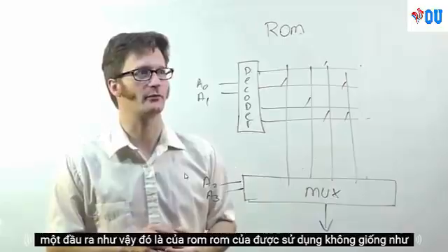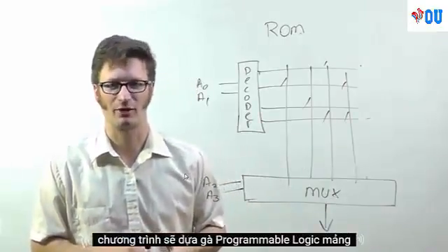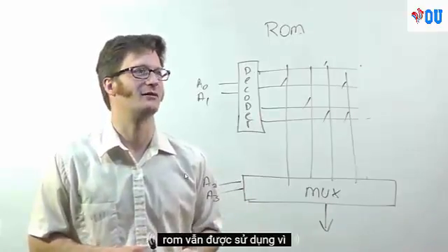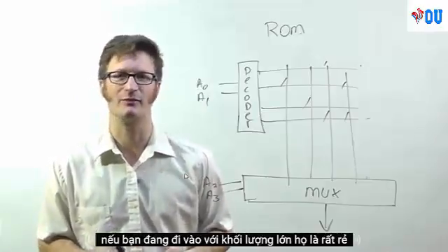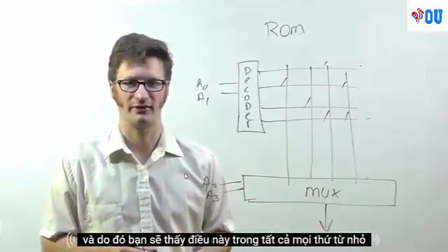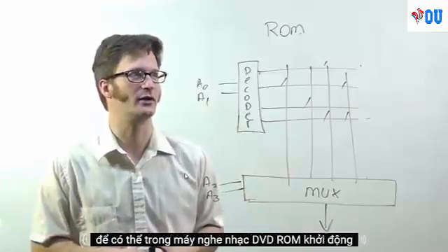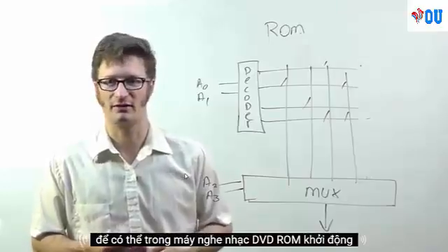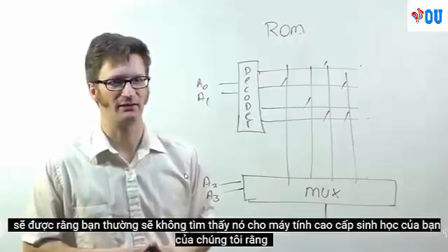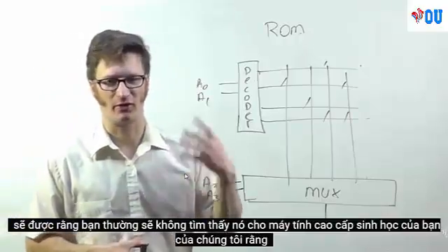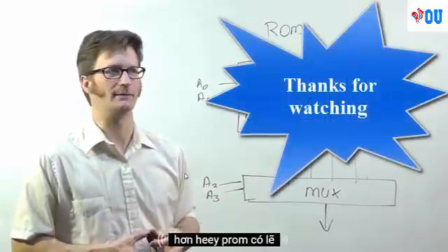So that's ROMs. Unlike the programmable array logic and programmable logic array, ROMs are still used because if you are going into high volume, they are very cheap. And so you'll see this in everything from little toys that have sounds encoded into them to maybe your DVD player, where the boot ROM will be that. You typically won't find it for your BIOS in your computer. That would generally be a flash ROM or EEPROM.